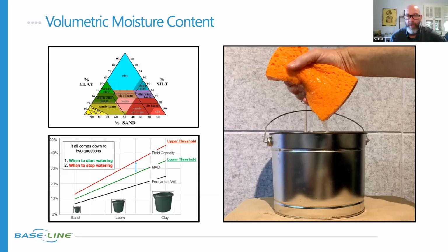It's also important to consider when runoff would occur as you're applying the water. So one of the key strategies when using soil moisture sensors when we're irrigating, that we'll talk about, is the cycle and soak process. Because if you just dump a bunch of water on that sponge all at once, it's not going to absorb it all. A lot of it will run off or not get utilized, and soil reacts the same way. That's right. When I pulled this out of my storage, the sponge was bone dry, and it took a couple of minutes and a little bit of working to get it to fully saturate. I like that. Yeah.